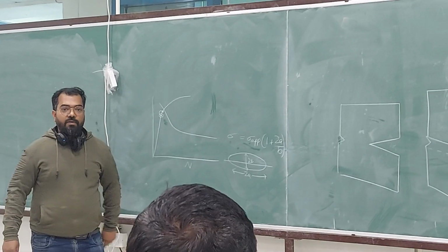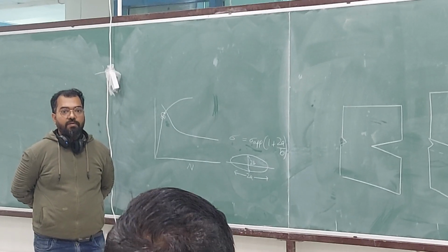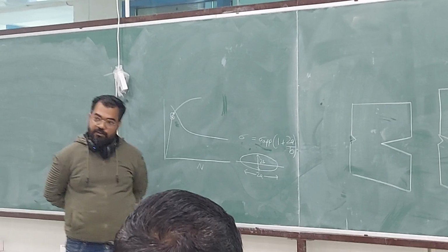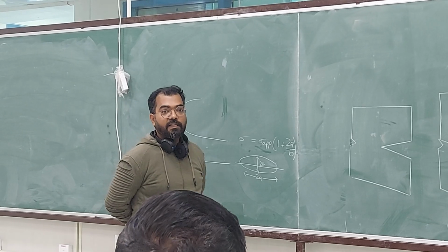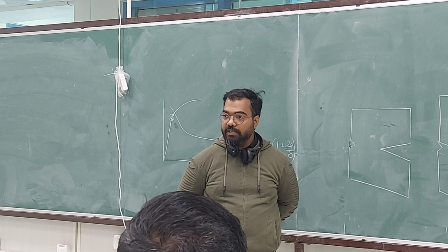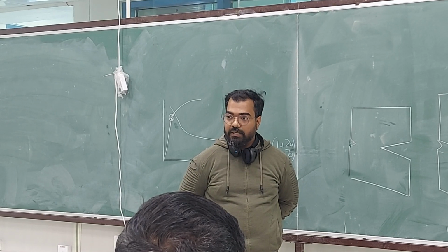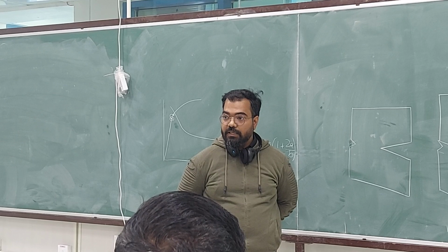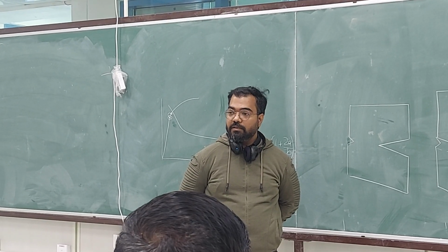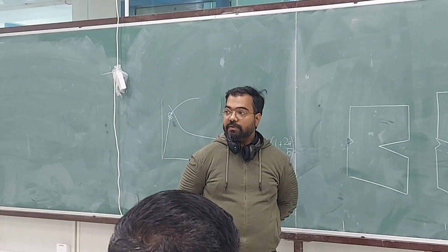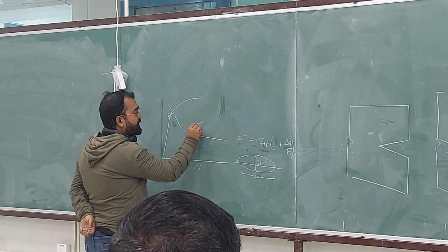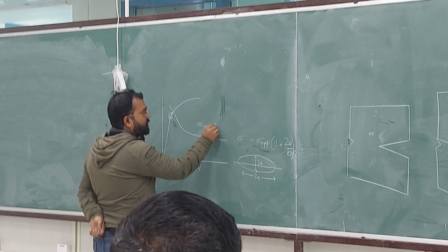Sir, in low cycle fatigue the stress amplitude value is higher. How much higher, how much lower? Than the yield strength. Yes. So the difference between low cycle and high cycle fatigue is that in low cycle fatigue, stresses are higher than yield, so you have plastic strain there. Basquin's law and low cycle fatigue is related to plastic strain. Okay, we will discuss that fatigue also. And in high cycle fatigue, stresses are lower than sigma naught. So here, the applied stress sigma max is lower than sigma naught.